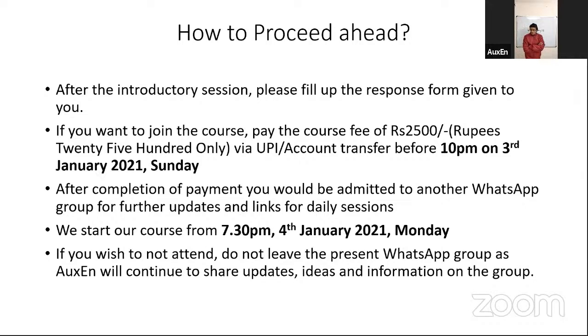Okay. So I will tell you the clauses where you are allowed to increase the bearing capacity by 25%, or where you are required to do what? Yeah, mainly the bearing capacity increase of 25%, or what all other issues are involved in IS 1893 related to footing design.